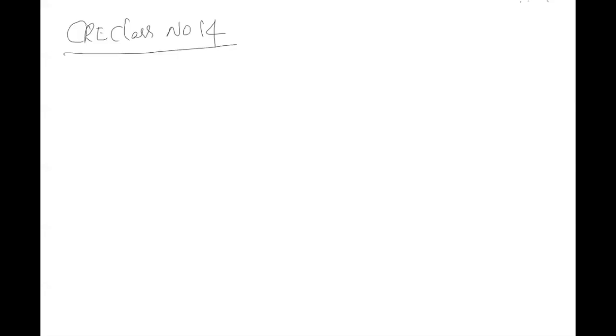In pulse experiments, the red fluid is not continuous. Imagine that you have a house. White dress people are coming in, white dress people are going out continuously. Suddenly, to the white dress people, you add 10 red dress people. Are the 10 red dress people continuous? No, non-continuous. The 10 red dress people are injected along with the white dress people. Now you sit at the exit and count how many red dress people are coming out with respect to time. Clear?